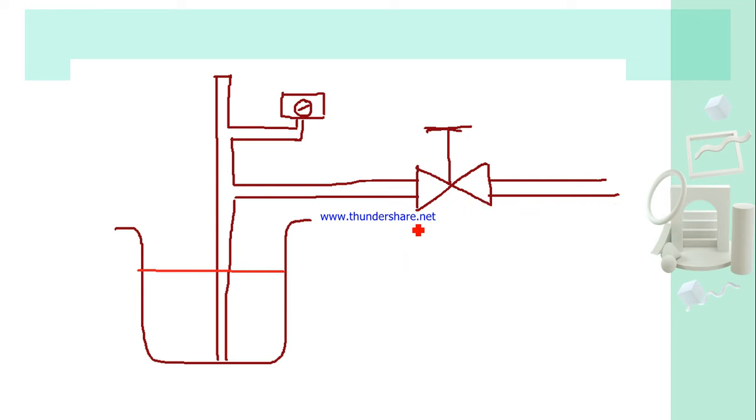So this is a flow regulating valve. Here you can use some compressed air, and this is a tube. This tube is inserted till the bottom of the tank or container of which you want to measure the level, and with that one pressure gauge is connected.